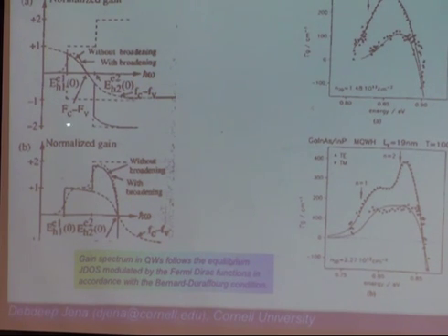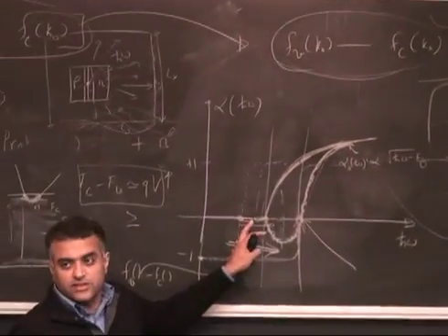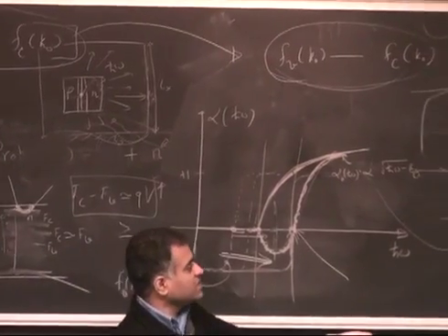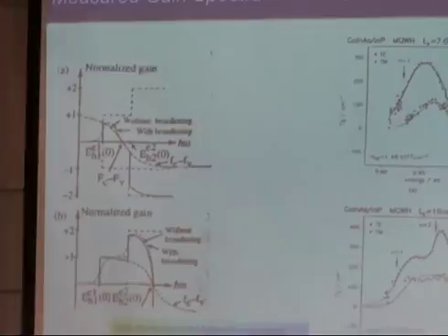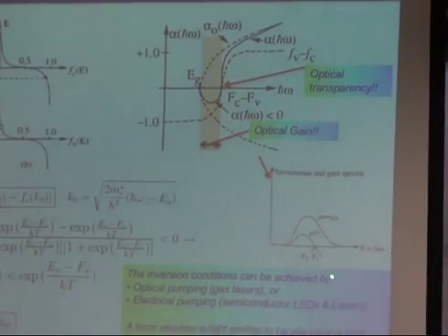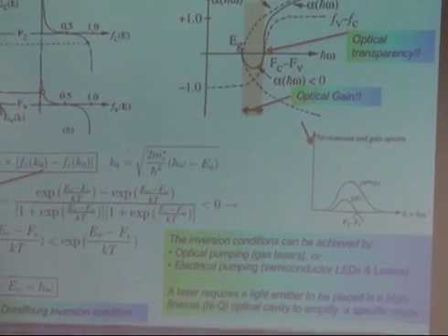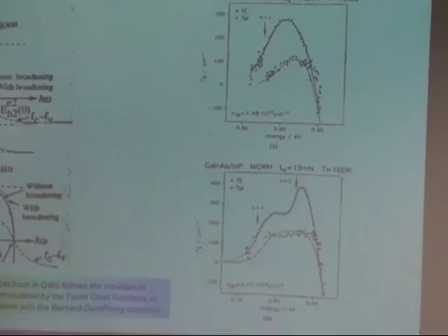So now, for example, instead of the band diagram, you can plot the gain, as we were plotting. Now, what is the gain spectrum of a laser? It may seem fancy, but essentially all that it is is this flipped upside down. That's the gain spectrum. As you can see, minus alpha is gain, right? And so this is the plot. For a bulk material, the gain spectrum looks just like this curve here. And for a quantum well, I think you know by now why.